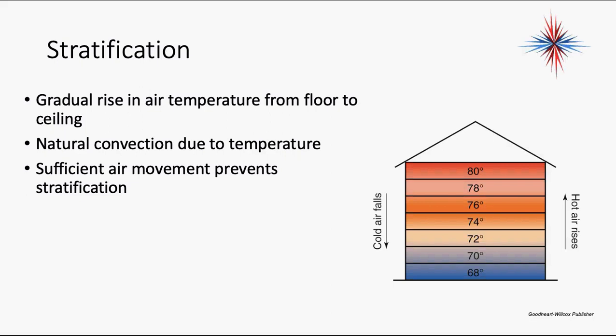Again, we can create the air pattern for our normal situation. Because we want the cold air to stay at floor level, be sucked into the return, and we want it to mix with the warm air being blown out of the supply registers. Now, when you have a second floor, they may be in the ceiling, but we do also create the air patterns because of the fan speeds. I could create sufficient throw from those registers to fix the stratification problems.